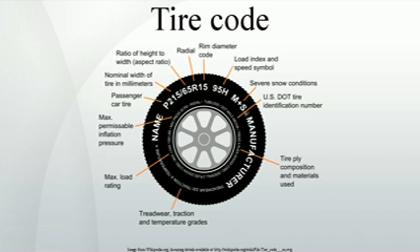TL, tubeless. TT, tube type, tire must be used with an inner tube. Made in country of production. C, commercial: tires for light trucks, example, 185 or 14C. B, bias belted: tires for motorcycles, example, 150/70 B 17 69H, diagonal construction with belt added under the tread. SFI, or inner, side facing inwards: inside of asymmetric tires. SFO, or outer, side facing outwards.